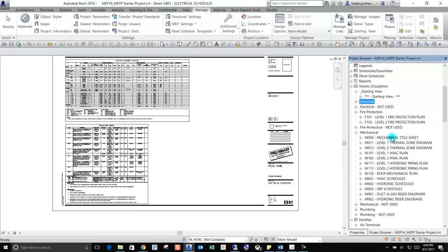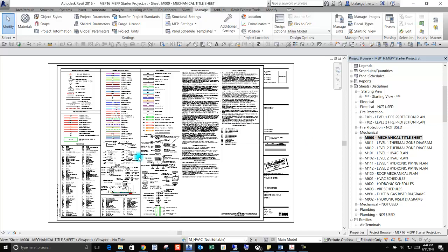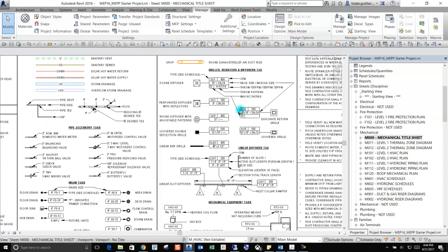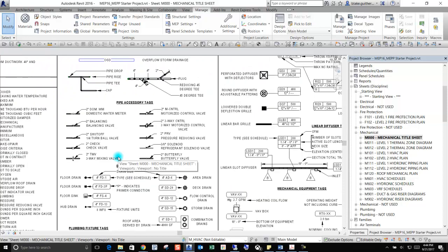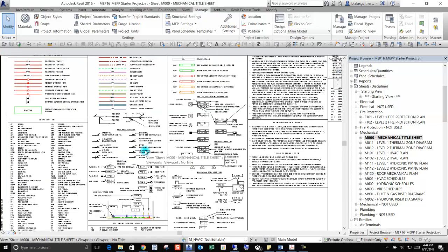And I guess the last piece I'll show is our title sheet. Mechanical and electrical use dynamic title sheets, which isn't Legends in Revit. It's based upon design options and placing elements on non-primary design options. So they're not included in schedules and not seen by other disciplines linking in our model. But you guys will be able to see this and modify it once again. So that's the sample project.